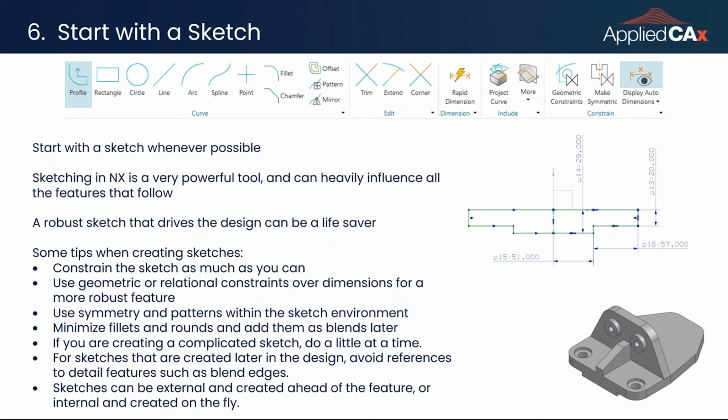Use symmetry and patterns within the sketch environment as well. It's not just outside of the environment. Try to minimize the fillets and rounds that you add, and just create those as blends towards the end of the part. This makes your life a lot easier as you're making changes and adding additional features if you haven't added those blend faces to the part yet.